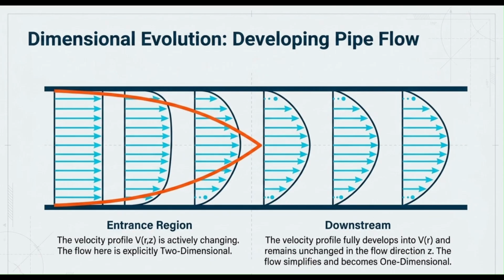The length of the arrows corresponds to the magnitude of the velocities at those locations. You can see the velocity gets reduced near the wall, but it gets compensated and increased at the center. Further downstream, the velocity profile becomes fully developed.